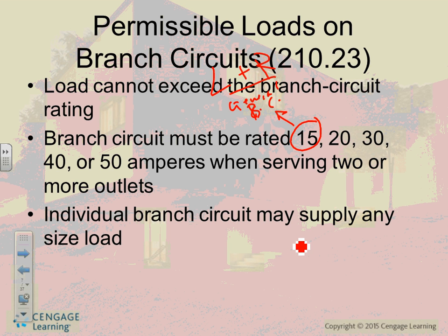All right, what wire size do you use with this guy? Number 14. Okay, so now let's go to the next one. Next guy, where do you use a 20 amp circuit in a residential? Kitchen. Thank you. How many for the kitchen? So right here, 2 for kitchen. Okay. 1 for bathroom. What else? 1 for laundry.